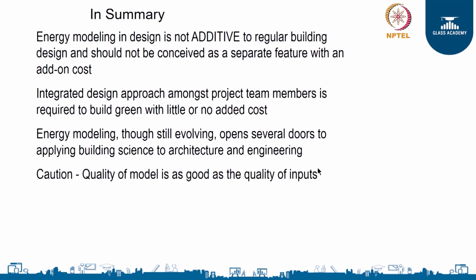So what happens is, throughout the life cycle of your building, this model is evolving and it's always calibrated to the actual performance. So tomorrow when you do an energy audit and you are finding certain energy conservation measures, you can put these energy conservation measures into the model to see how much benefit you get, and you can start looking at cost benefit analysis and what is the percentage savings you will get. All those things can be done for every retrofit that you intend to do during the operations of the building. So that makes it even more effective.